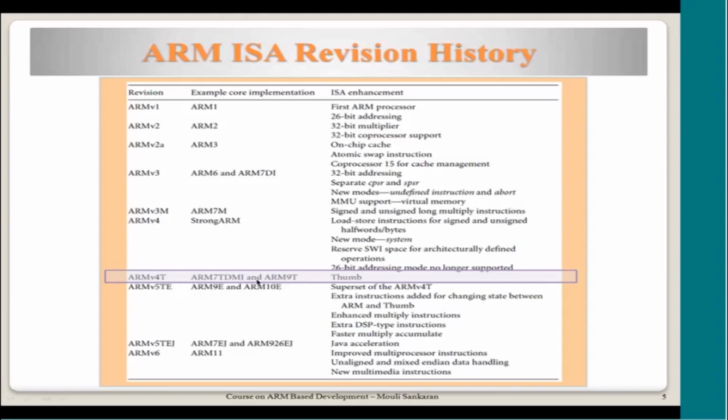So this will ring a bell that I mentioned in the last class: when a particular instruction, while executing, is accessing R15 from the register file, it is expected to get the address of the current instruction being executed plus 8, because that is what ARM 7 follows. So ARM 9 also simulates that. In the 5-stage pipeline it would be plus 4.